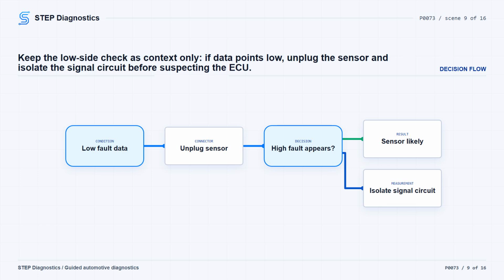If it does not, disconnect the ECU harness connector to isolate the circuit. Then check the temperature signal circuit for continuity to both chassis ground and the sensor ground circuit. Continuity there means the signal circuit needs to be repaired for a short to ground or to the sensor ground circuit. If the signal circuit is not shorted, the ECU only becomes a supported suspect after that isolation check.